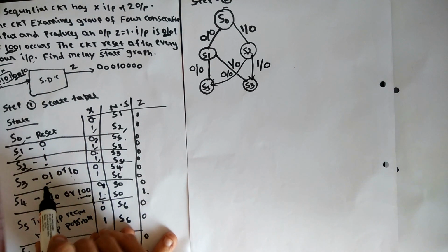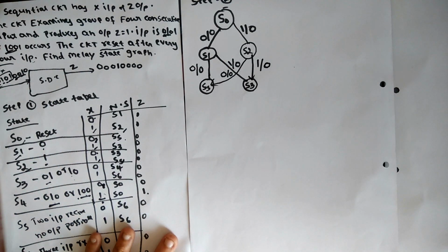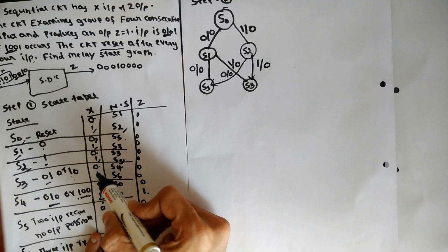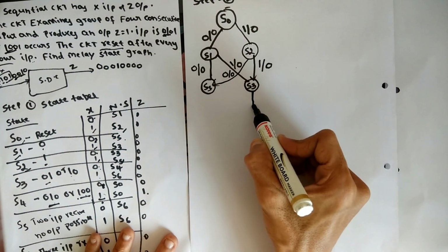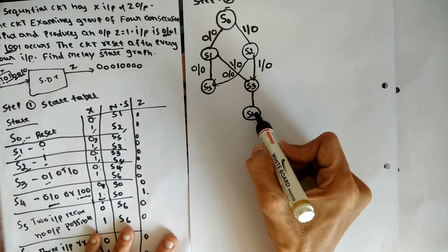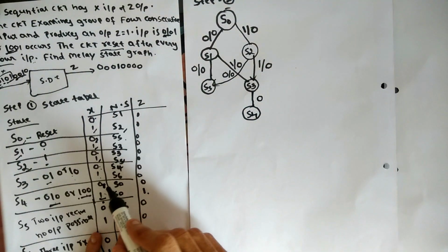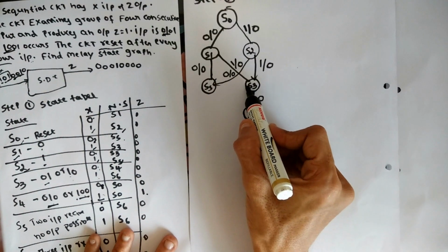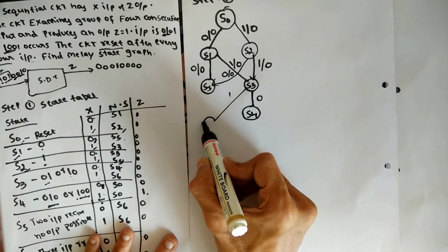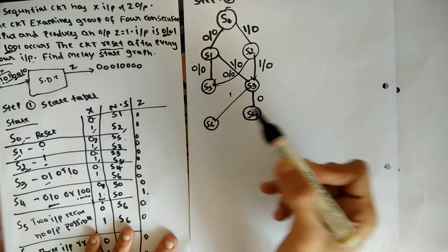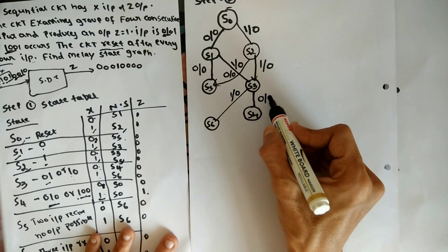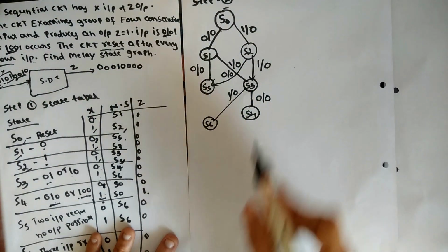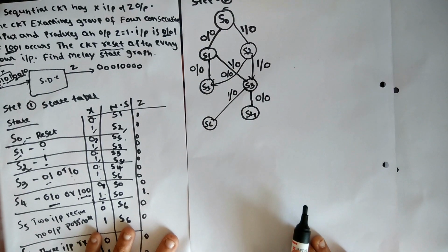Now move on to the S3. S3 has again two states, one is 0 and 1. When 0, it is going to the S4. So take S4 here when it is 0. When it is 1, it is S6. So make it 1 and it is S6. So in both these conditions of S3, only 3 numbers have come, so Z is not a possible output. So make it Z is 0.